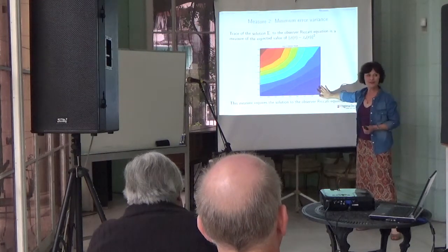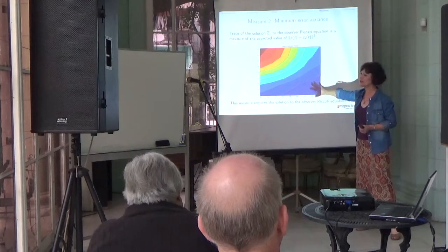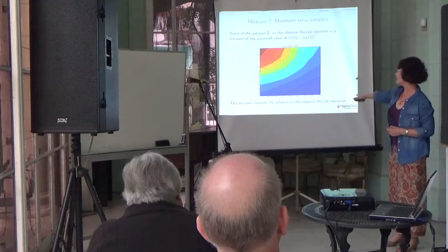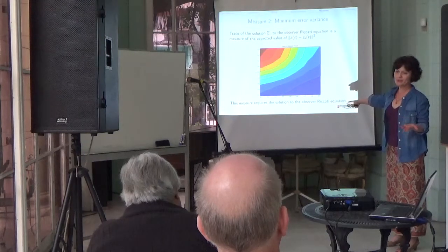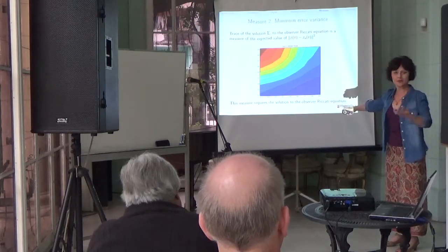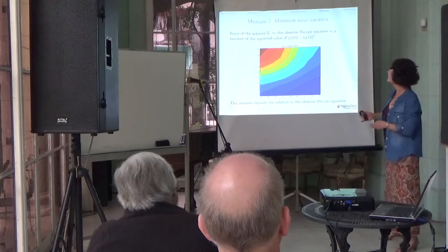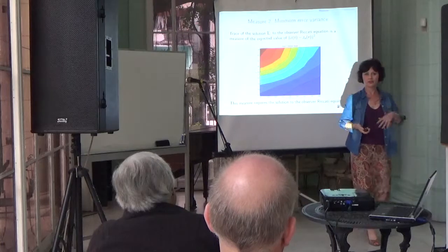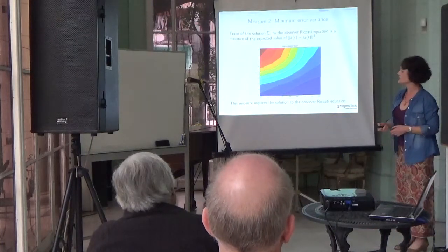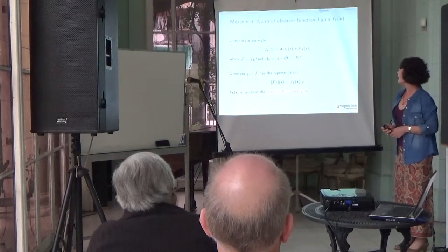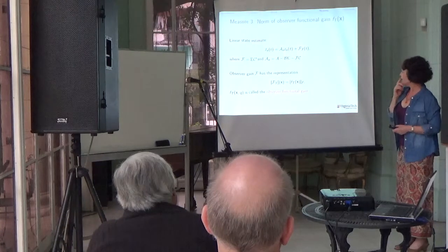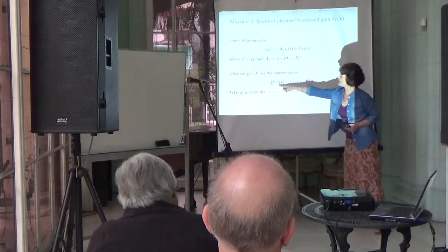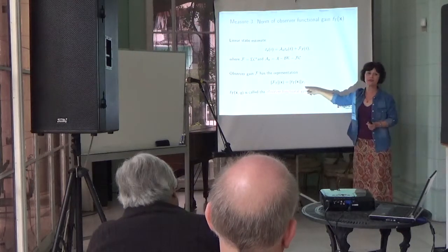And we want the error to be small, so this region is a good location. Just pointing back, this measure requires a solution to an algebraic Riccati equation, so that's what we need in this case. So we look at the trace of the solution to the operating Riccati equation. The trace is very easy, but the solution is the problem. So under certain conditions, one can get this input operator to have a representation of this form.